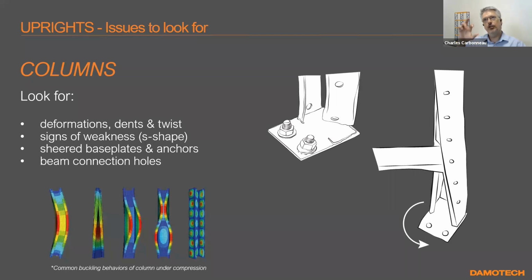And the beam connections: for cold form racks, you have these teeth that come in and attach on the columns. Sometimes they are torqued from a specific incident. If they are deformed, you don't have the same lateral stability. Which brings me to another question that somebody was asking: can you mix different types of teardrop racks from different manufacturers?